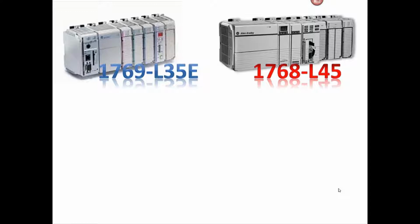So you need to keep your part numbers straight. Everything over on the left is 1769. Everything over on the right is 1768 until you get to the processor. And then if you keep going to the right, that's 1769. So you use the same I/O cards on both of these platforms.